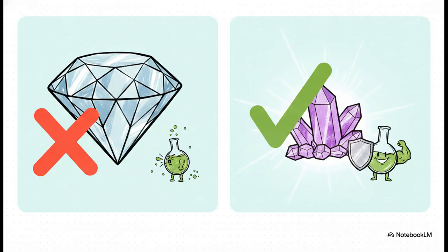Platinum is incredibly expensive. And remember those impurities we just talked about? Platinum is very, very easily poisoned by them. So, the crucial point here is that modern factories almost universally prefer vanadium V oxide. It's way cheaper, and it's far more robust against any lingering impurities that might have somehow snuck through our purifiers.